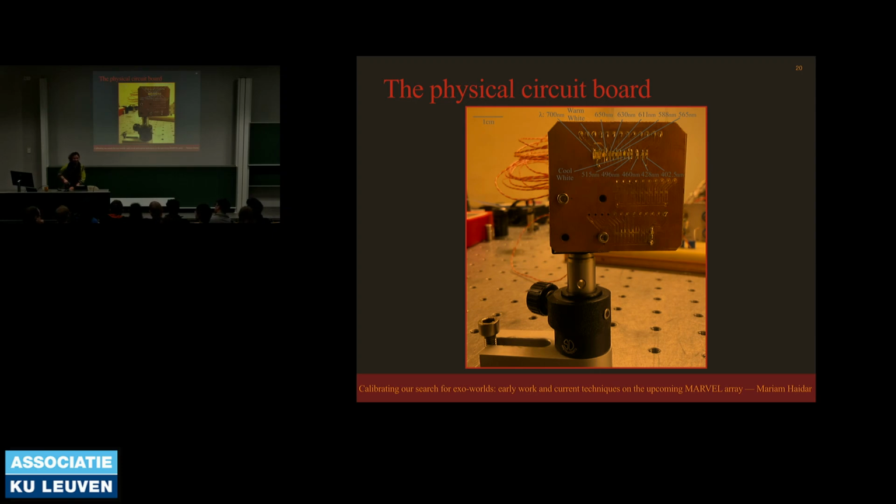Yep. Although I have seen white light LEDs with the phosphor layers that actually have a very, very broad phosphor re-emission peak, say, and very, very tiny blue end. So I think there's room for that. Yeah, I think there can be, and I think a possible solution is maybe using one of those, and then maybe using a collection of a couple or a few other wavelength LEDs that would fill in the gap, because the profile tends to look like this. And if you could fill in that gap sort of in the middle, that would be great.